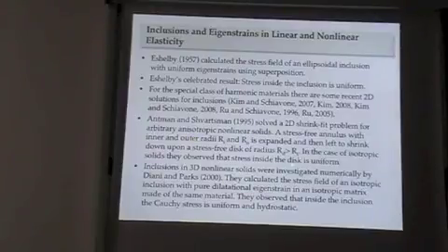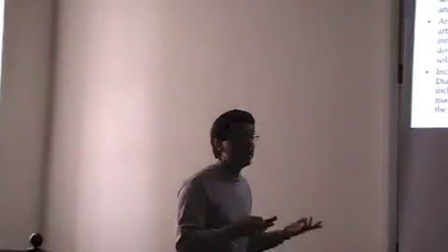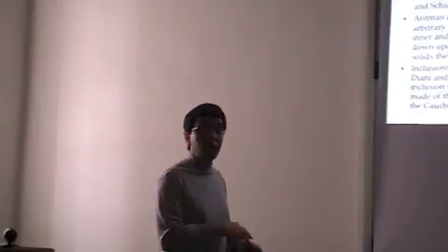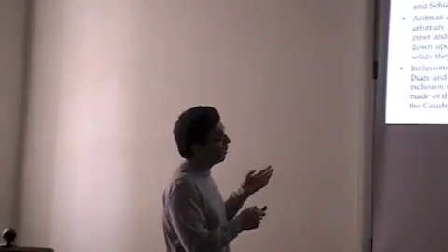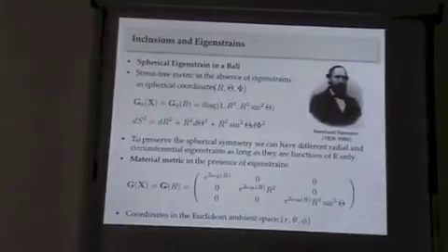And in 3D, the only existing result, as far as I know, is a numerical result by Dayani and Parks. They look at some finite element solutions and see that, yes, the stress inside the inclusion is hydrostatic if the eigenstrain is purely dilatational. So I'm going to prove this analytically for a ball with that inclusion. There hasn't been anything for 3D, and I'm not going to be restricting myself to harmonic materials: arbitrary isotropic, and then some class of compressible solids that include harmonic materials.